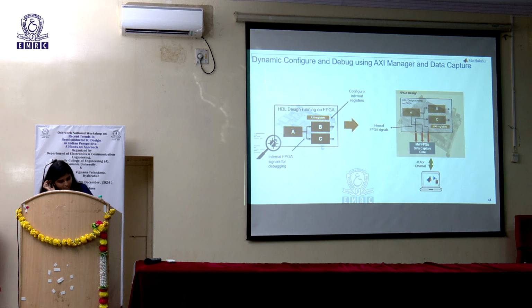And the FPGA data capture is something interesting where you can choose your signals. Suppose you feel the SSB is not getting detected, so you can choose the signals there and name them as test points, and on the FPGA you can collect those signals directly into MATLAB and verify them. So this is one way which makes it a lot easier for you to use a known environment to debug things on hardware.